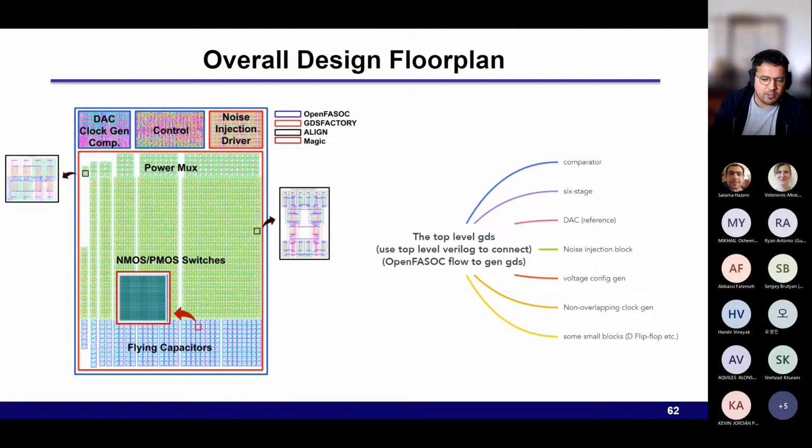Let's say if I want to tape out in GF12 right now with the open source tools, I can just do it using the rule deck from the foundry, the DRC and LVS rule deck. So we need to find a way where we can import those rule decks in KLayout and Magic, and it should be doable. To comment here, the problem is IP protection because the SVRF language by Calibre is owned by Mentor, and they are very picky about implementing it elsewhere. So what is the solution for that, right? Are there other ways to do it?